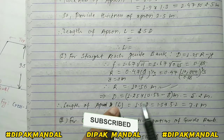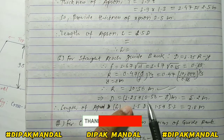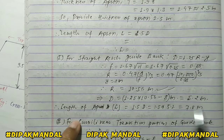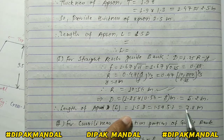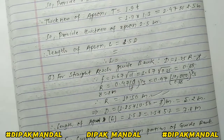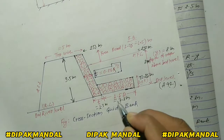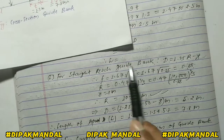And now we have to calculate D equal to 1.25 (R minus y). Okay, then we get the value of D equal to 5.2 meter, and length of apron L equal to 1.5 D, and D is taken 5.2 meter. This becomes 7.8 meter. Okay, so you have to write here this is the length of apron, and this becomes 7.8 meter. Okay, this is for the length of apron for the straight Guide bank.